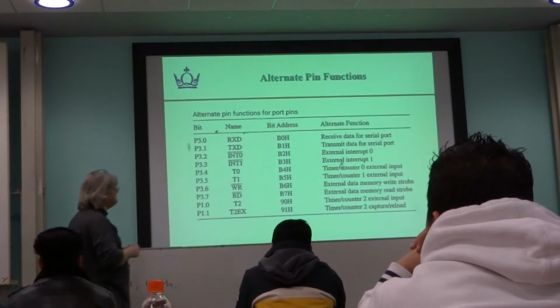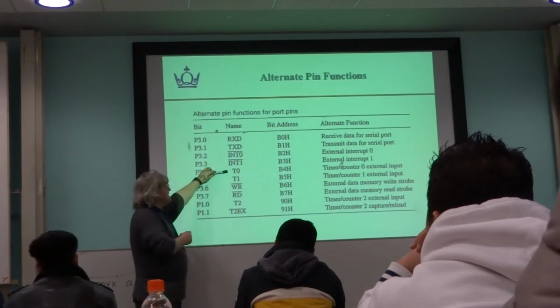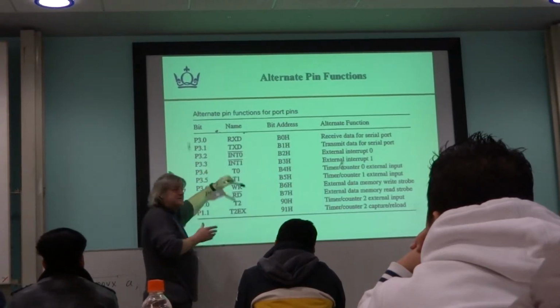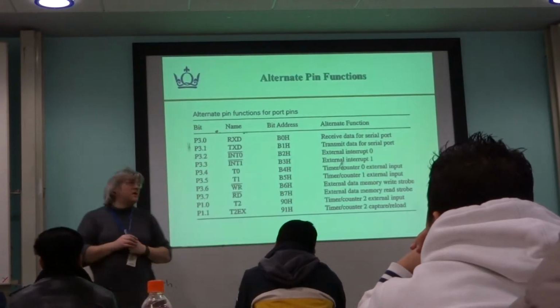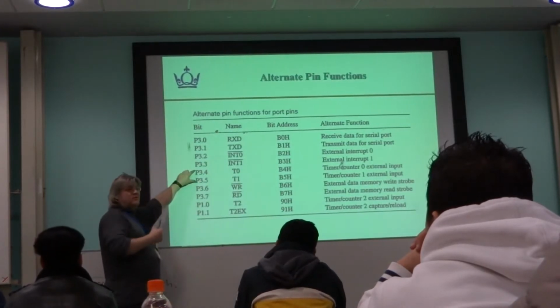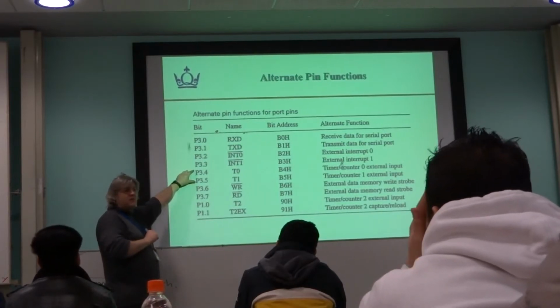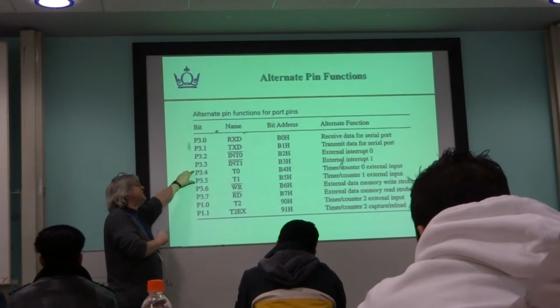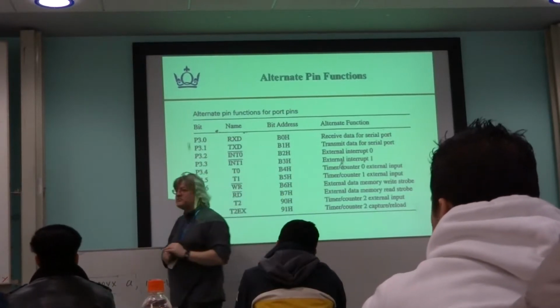No, that's not possible. The next 2 things are connected to timer 0 and timer 1. The 8051 has 2 timers built into it. Now, you could use this, for example, rather than use the microcontroller's internal clock to increment the timer, if you want to use some external clock source. That's one reason. Or you can actually use these timers not as timers, but as counters